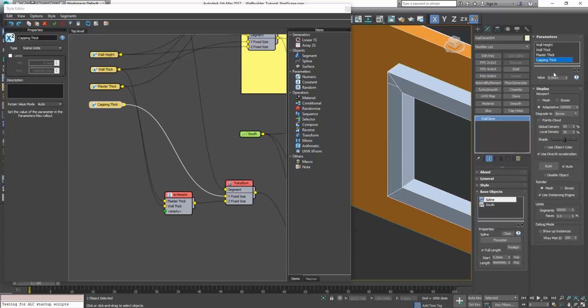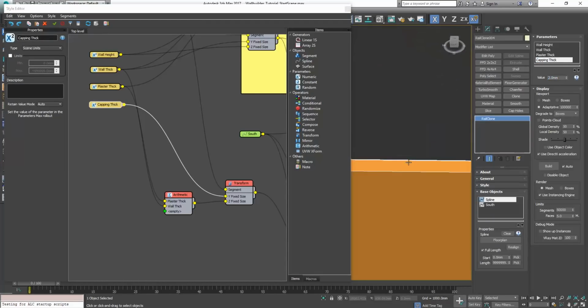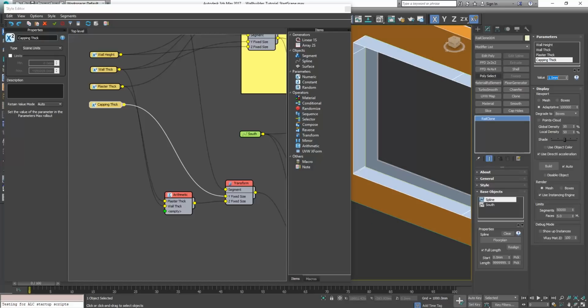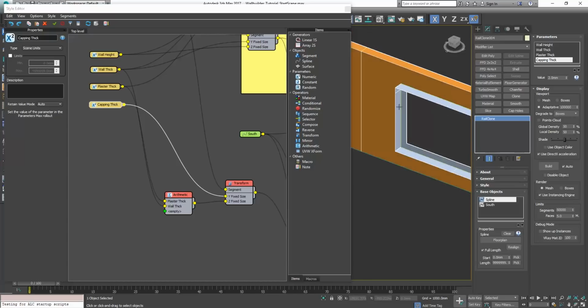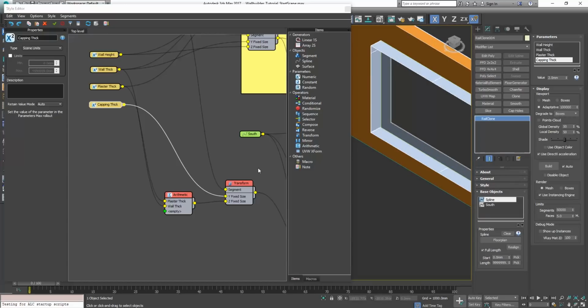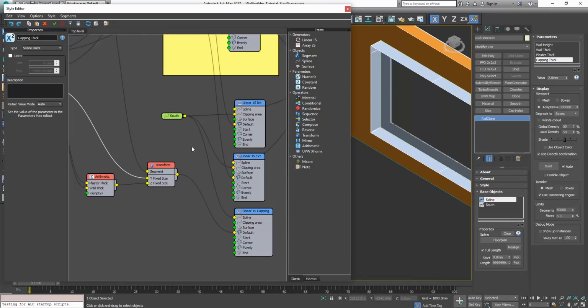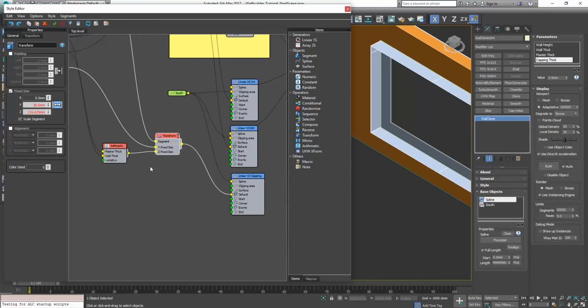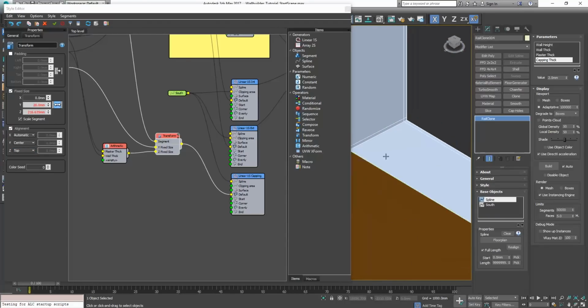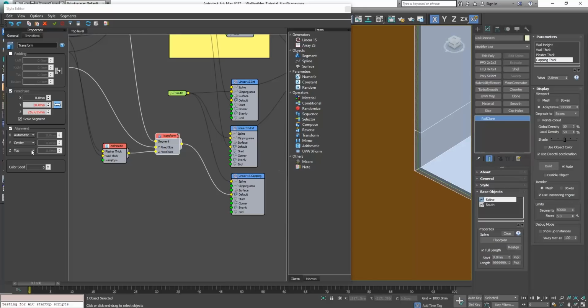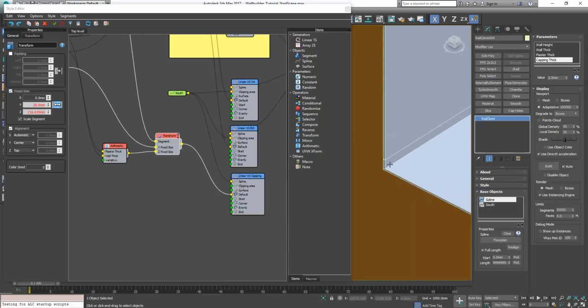So they can just come into here and say, oh, I want it to be 2 mil around that edge, or 1 mil. It's just a capping, so you can do that as you wish. I'm going to leave it at 2 mil. Okay, all well and good. Now, you'll notice the position needs to be shifted to the inside of that wall. So, let's see if we could do that through the transform first. And we'll have a look at our alignment methods. Okay, so the top of the Z seems to be where we need it.